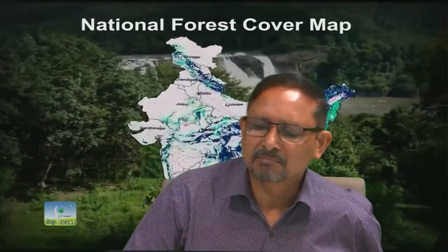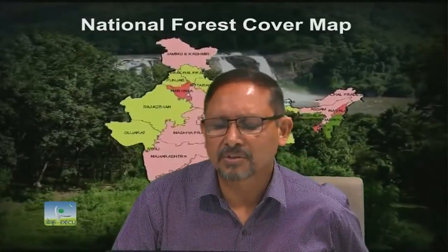How can we remove artifact heights from freely available SRTM or ASTER data? It is very difficult to remove artifact heights like trees. Sometimes you know that an area has forest of almost equal height, suppose 30 meters, so you can subtract 30 meters.